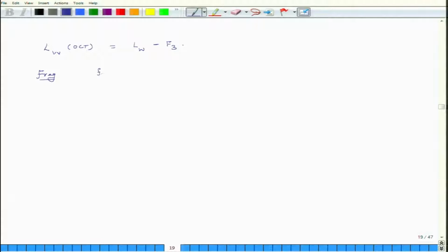The first frequency we look at is FM over 32, FM over 16, and FM we know how to compute, FM over 8, FM over 4, FM over 2, FM, 2 FM, 4 FM and 8 FM. First we compute the value of FM. These are again octave bands, but they are not industry standard octave bands, but we will figure out how to connect the industry octave bands with these bands through an example.